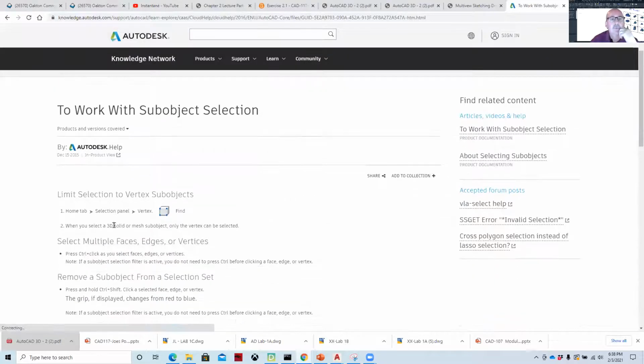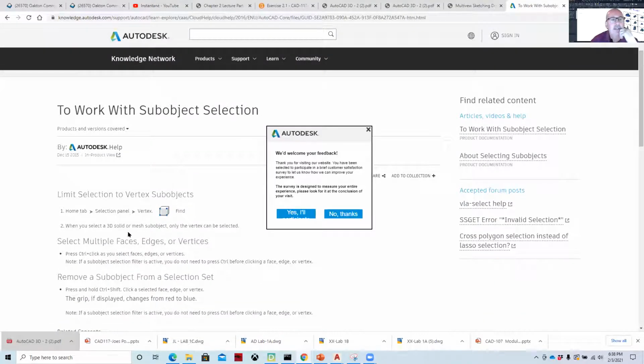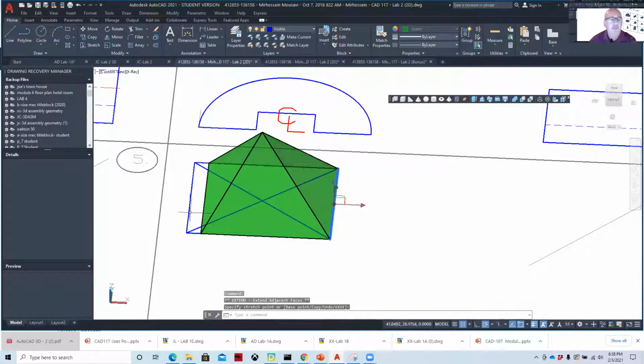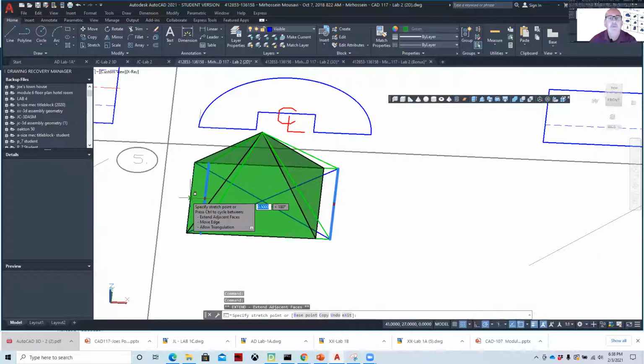And so what you want to do is to be able to get these grips on it. And so it is control click that you can do that with. And so if I come back here and I control click, then I can grab that grip. There we go. Control click, and I can grab this one. And then will just bring them partially.